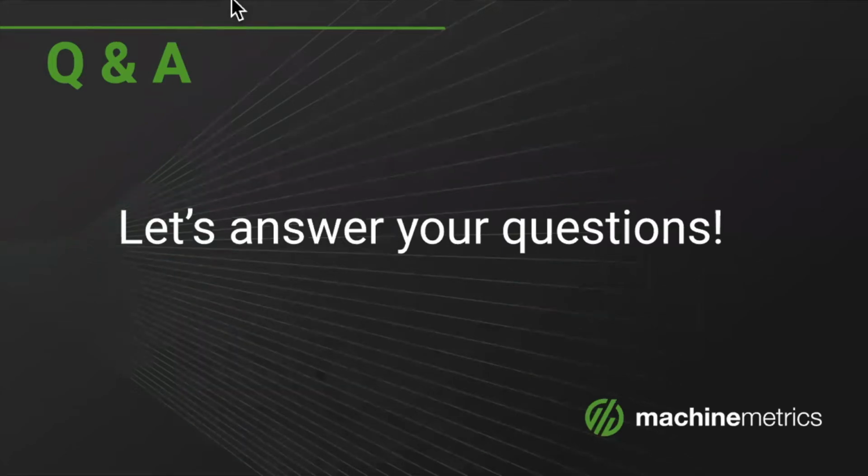So the good news, though, is that when you create jobs in MachineMetrics, you can put in for those values really any value. So when I've worked with customers before that didn't have job standards or setup standards, what we would do is we would take an educated guess. So maybe we'd say, okay, we're going to start with the basic presumption that all of your setups are 2 hours. Then as the jobs run, we will refine those standards. So job A actually took 1.5 hours, job B took 3 hours. And so the next time the job runs, it's not wrong a second time, or on an ongoing basis.